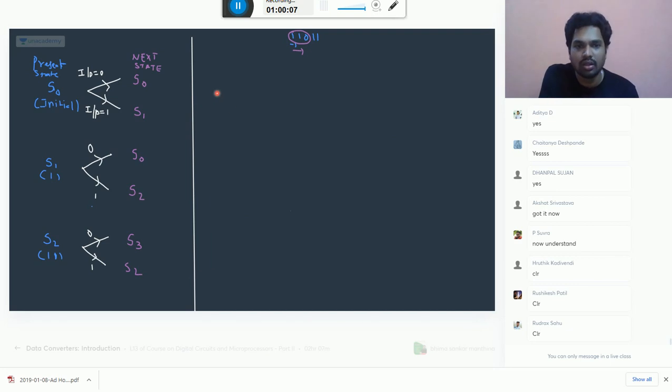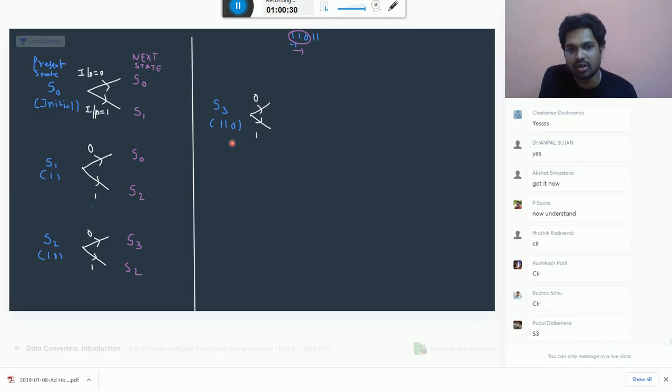Now listen here. Again, same story. What is that? You are in the new state S3. What is the meaning of S3, sir? Double one and also 0 has occurred. Now again, two possibilities are there. Your input can be 0, input can be 1. See, after double one 0, if 0 occurs, where to go? Arey, why S3? By double one double 0 is not your sequence, man.